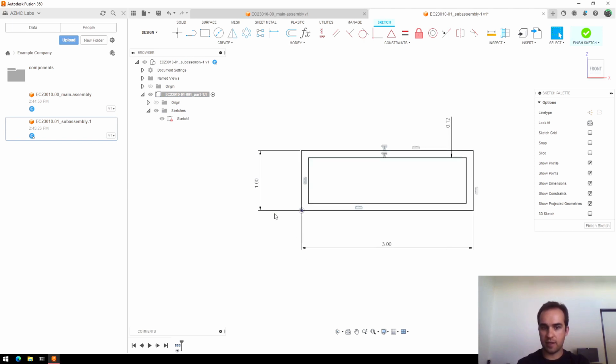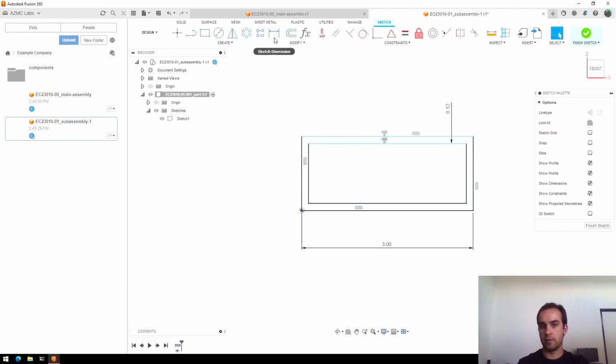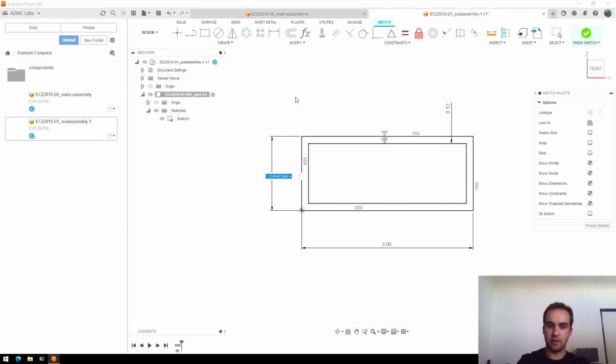Now, let's say I went and deleted this dimension. You'll see two lines turned blue, and the lock turned to a pencil. Now, if I try to drag it, particularly dragging one of these blue lines, you can see it has freedom to move. This is a problem because, if I drew a sketch like that, say I wanted a 1x3 tube and I drew the sketch like that, it looks like a 1x3 tube, but if I go to put the dimension on, it's not actually 1 inch, it's 1.24. So I'll place that dimension and I will type in 1.